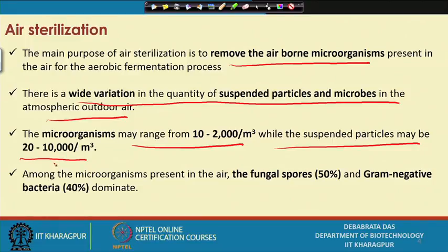Here I want to tell one interesting thing: usually the biochemical industry recommends a higher altitude, and we assume that at higher altitude the amount of suspended particles will be less, and if the amount of suspended particles is less, the microbial contamination also should be less. Among the microorganisms present, fungal spores, 50%, and gram negative bacteria, 40%, dominate. This is usually the case we have observed in the air.